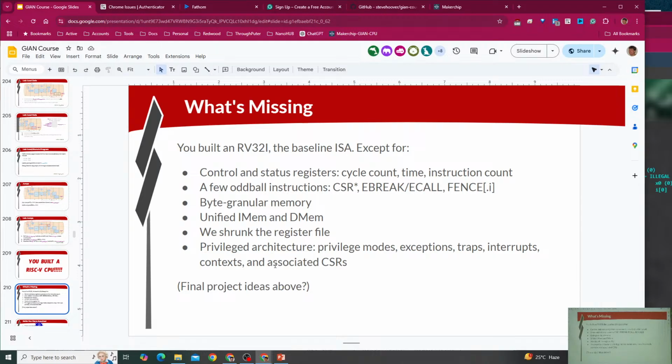On the actual system, there will be some flash memory that contains some privileged code that the user should not be able to muck with. And you need to be able to safely get that privileged code onto the CPU to work with the operating system, to provide proper protections to make sure the user code doesn't mess with things that it shouldn't be able to mess with. And so there's a whole architecture around that boot process that we ignored completely.